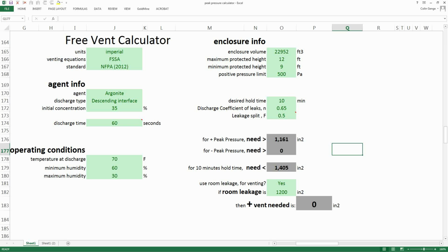I'm just going to take a quick look at the questions here, see if there are any of them that are room needs vents. So someone asked, if a room needs a vent, is it necessary to replace more agent? No. The need of a vent just says a room is a little bit tighter than it has to be. We don't actually lose much, if any, agent out of the vents, so that's really not an issue.